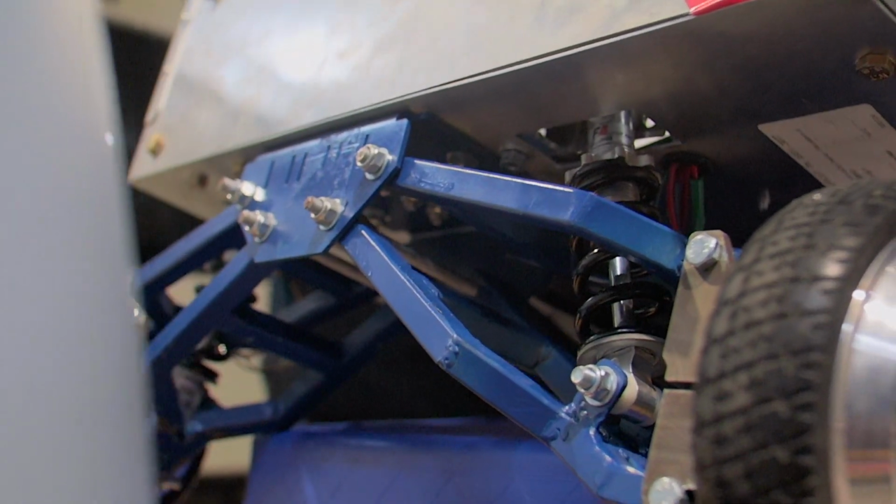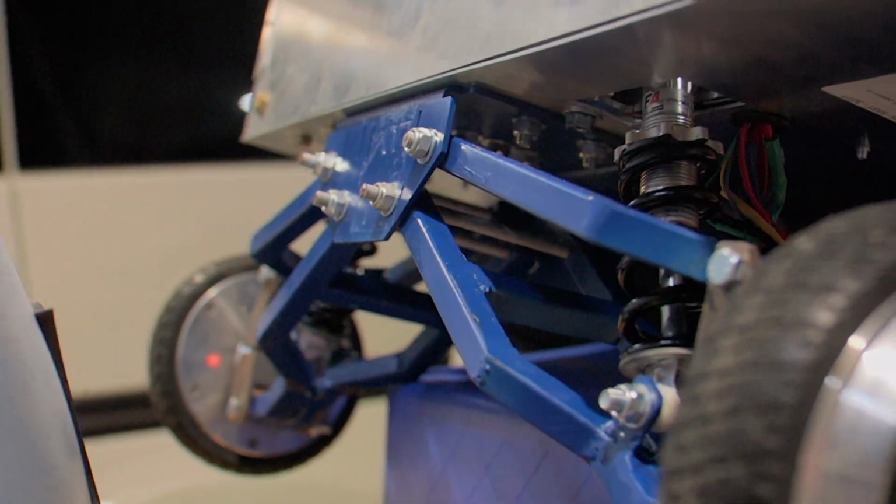The suspension system complements the drive with an adjustable double wishbone design for the front wheels and a 3-link Panhard suspension for the rear caster wheels. This setup evenly distributes the load and maintains traction, allowing the ADR to traverse rough surfaces like stones and cracks.